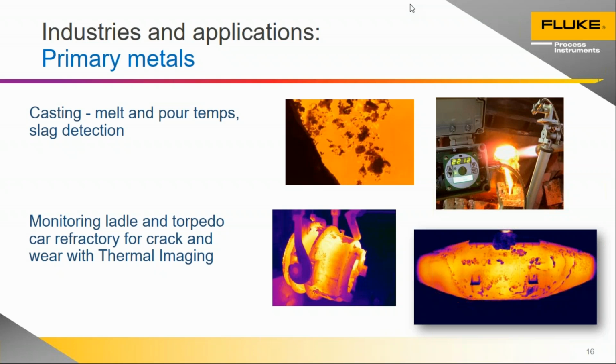Those applications can range from a tiny crucible of a precious metal inside of, say, an induction furnace to a really large scale steel plant, which most of you probably have a little more exposure to. And in those plants, you have pyrometers and other infrared sensors in lots of different temperature dependent regions of the plant. Some of the images you see here, I'll go through what you're looking at. On the left, you have an image looking through a window or a viewport into a vacuum furnace that has a super alloy material molten inside there.